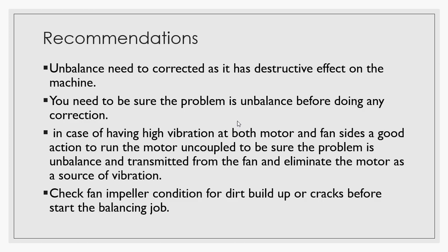In case of having high vibration at both motor and fan sides, the action is to run the motor uncoupled. For example, if you have a motor and a fan and you find high vibration at 1x on the motor and at 1x on the fan, but the vibration levels on the motor are higher, it could be a problem with the motor itself, like the cooling fan is broken, or soft foot, or excessive clearance, or even the motor itself has imbalance.